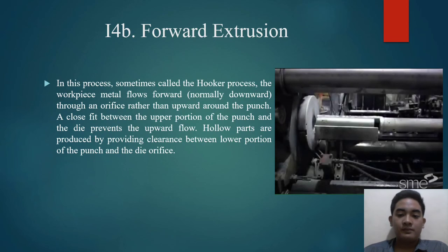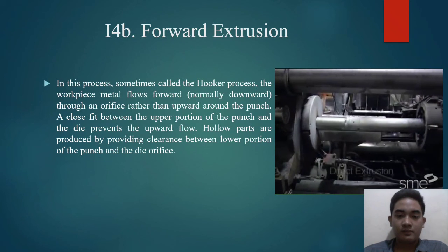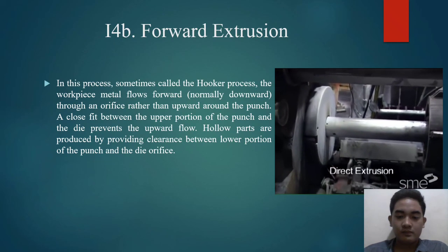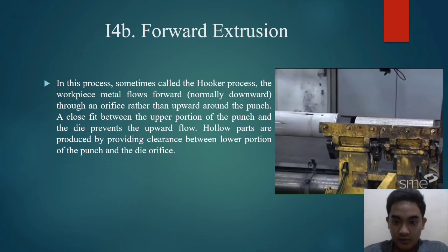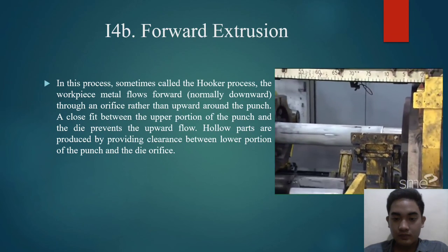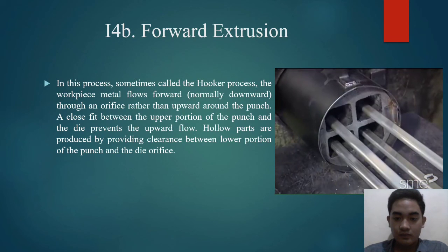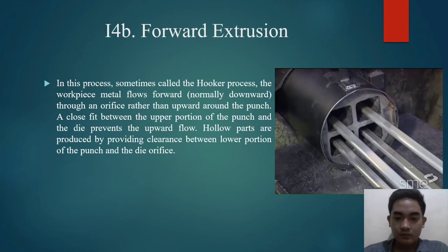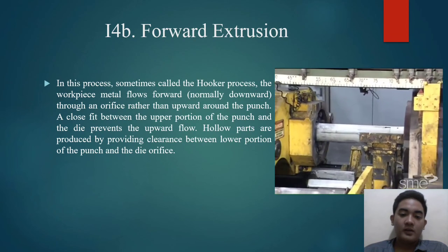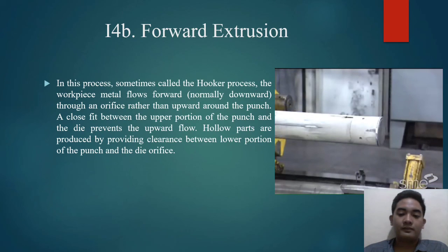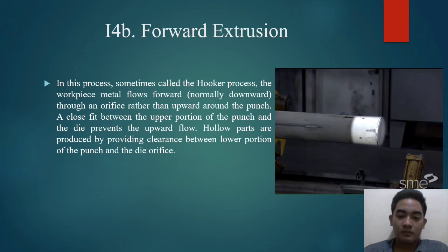The primary type of hot extrusion is direct or forward extrusion. In direct extrusion, the hot billet is loaded into a thick wall container and forced through an extrusion die secured in a holder. The force for extruding is applied by a ram, along with an intermediate reusable dummy block.